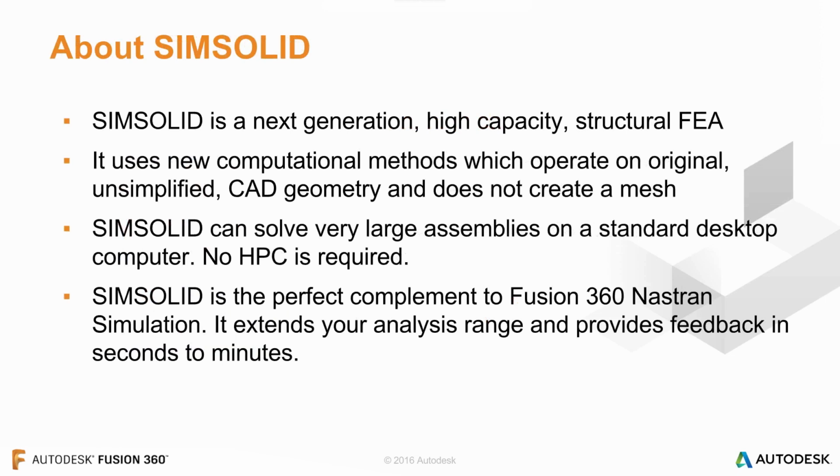Okay. Well, cool. So SimSolid is a new analysis product, and really remember just a couple things about it. One, it solves the original CAD geometry with no simplification. So you leave in all the detail and you just solve it as is, and it doesn't create a mesh. There isn't a meshing process.